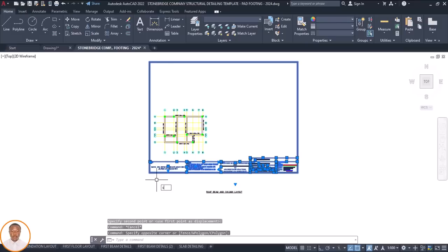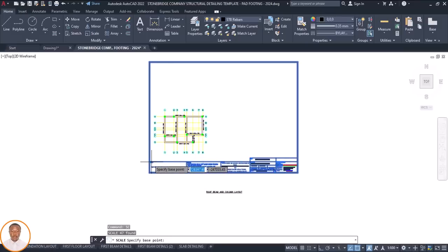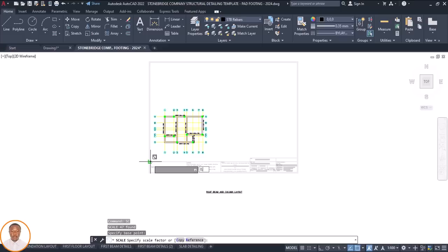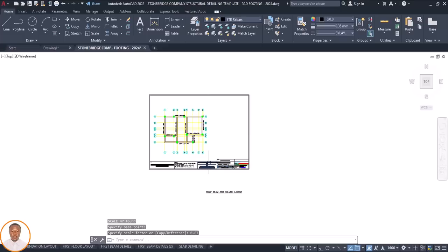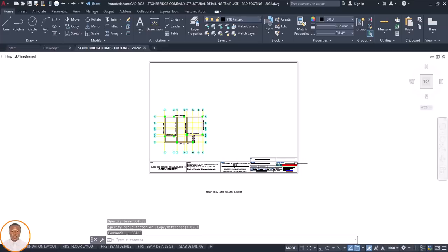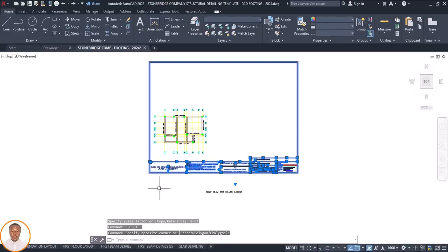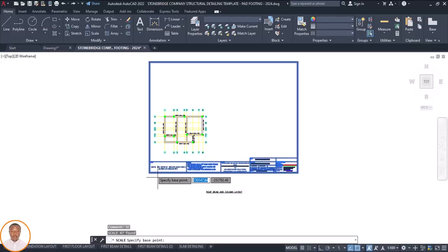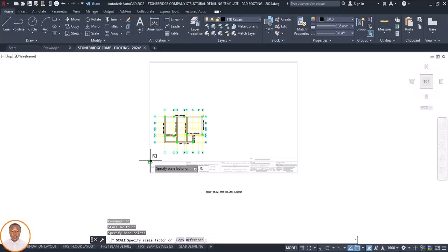Okay, that's SC, that's scale. Come to this edge here, at this edge here, 0.67, enter. Let's wait for it. Okay, it's small, it's not up to, it's okay, it's still big. Undo it, yes. Then 67, that's what we use, isn't it? 0.67. So I now press SC, enter. SC stands for scale. I'll come to this point here, click on it, 0.57, enter. So let's wait for it.